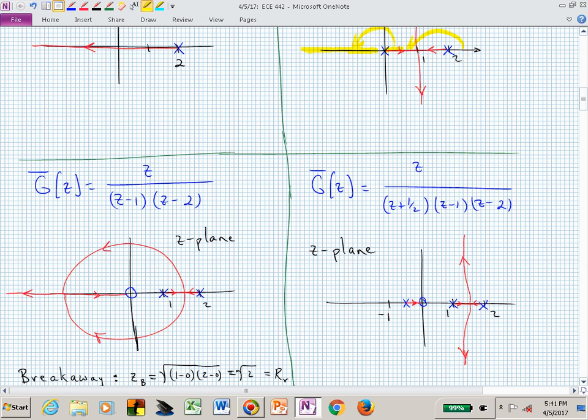And we will learn how to sketch this. In this particular case, when we have two poles to the right of a single 0, we actually have a circle that connects off the real line those real line segments. And we'll figure out how to determine where it breaks away. This is what we will call a breakaway point, and we will call this point the re-entry point. When does it re-enter the real line segment?